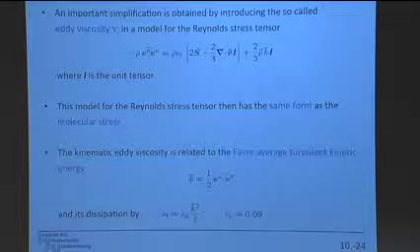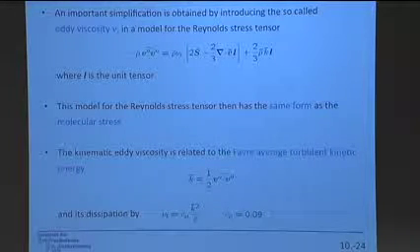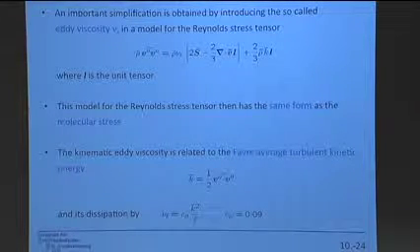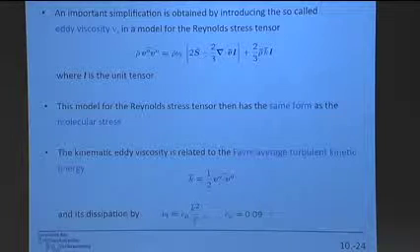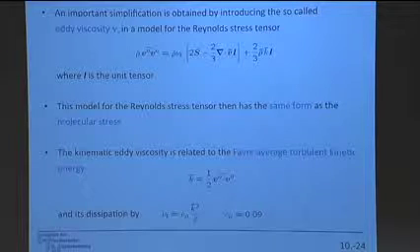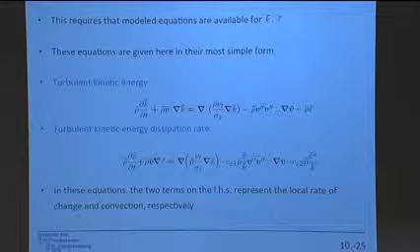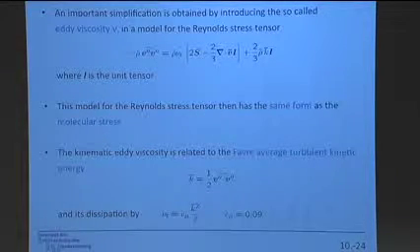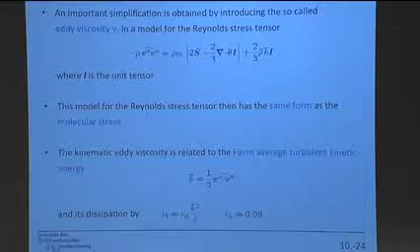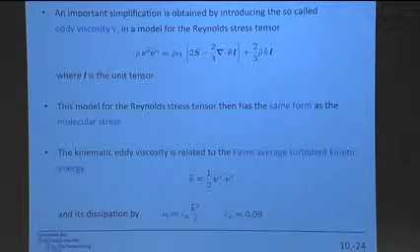Why do we introduce this here? We're not going to solve these equations. We just introduced this model to say that when we want to do scaling for turbulence quantities later on, we often use k and epsilon to represent velocity scales and length scales. Okay, so in the k epsilon model we went backwards actually. I said here we had 9 unknowns, but we reduced it to 1 unknown, and now we went from 1 unknown back to 2 unknowns. So we need equations for these 2 unknowns.